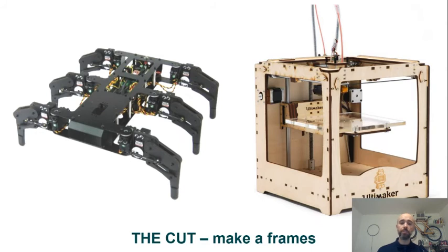The first thing you can do with cut pieces is to put them together to create a frame, a structure. Now, lasers allow you to have very precise parts. So even if you want to make something that moves, it's easy to create mechanisms. In this case, you see you have screws that work as hinges in a pretty complex robot. On the other hand, you can create pretty rigid structures from simple panels just because you snap them together, screw them together, or glue them together.